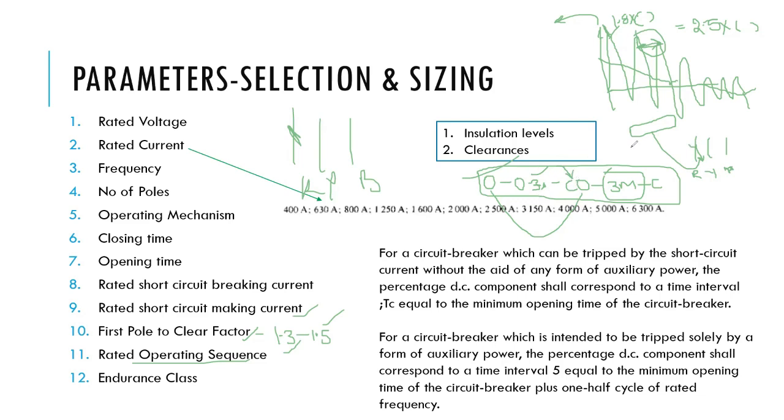If it really is a transient fault, okay, no issues, it will run. But suppose in the worst condition it is a permanent fault, not a transient fault, and I close it. Again it has to open, immediately it's opening. But due to these two openings, two shots, the SF6 gas is losing its dielectric strength.